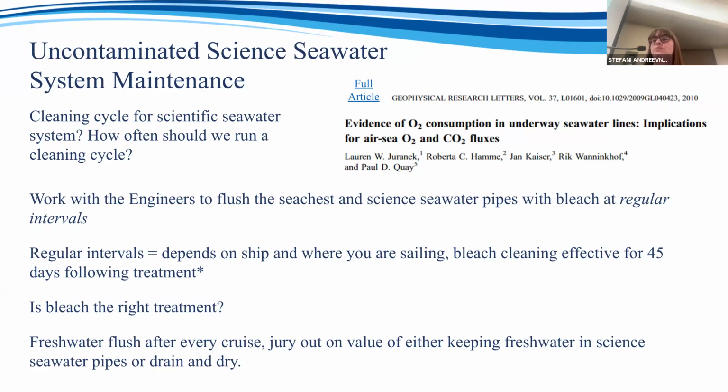From personal experience, letting bleach sit on your pipes and your O-rings and your PVC for days on end is very bad. I see very high failure rates from that, but if it's just a flush for some amount of time and then flushed with non-bleach water afterwards, you're going to get much better results. Yes, thank you. I should put that clarification in here. By bleach flush, I mean you flush it with the bleach tab and then you flush it very well with fresh water after that. You don't want bleach sitting in your pipes.